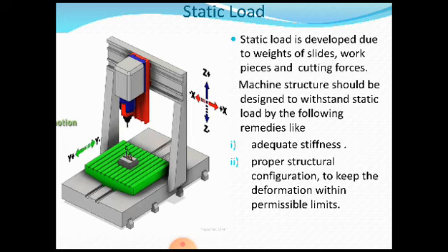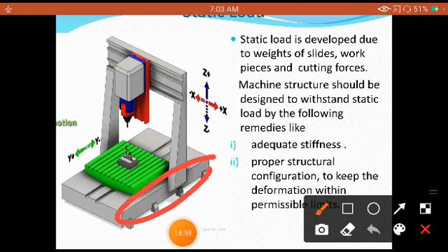Static load is developed due to the weights of the slides, workpieces and cutting forces. The weight of the slides, the weight of the workpiece and the cutting forces come directly on this base, which holds the columns as well as the bridge and the tool slide.